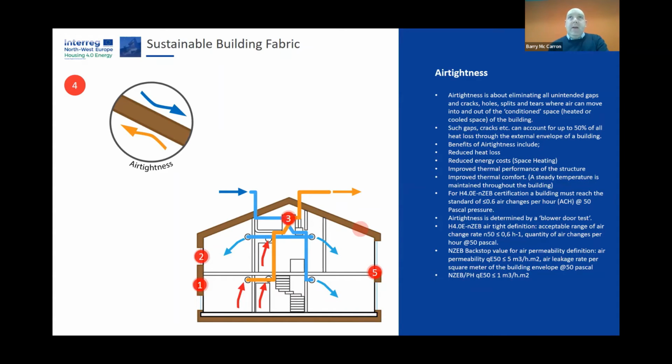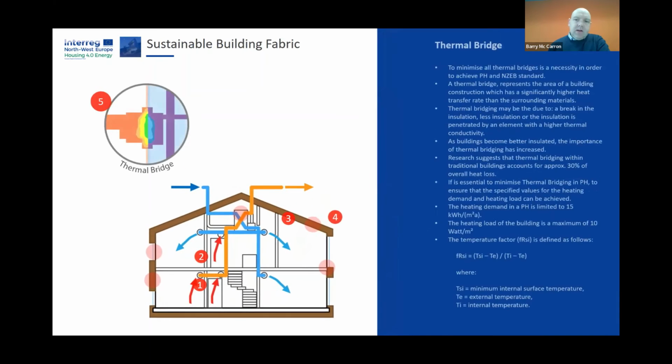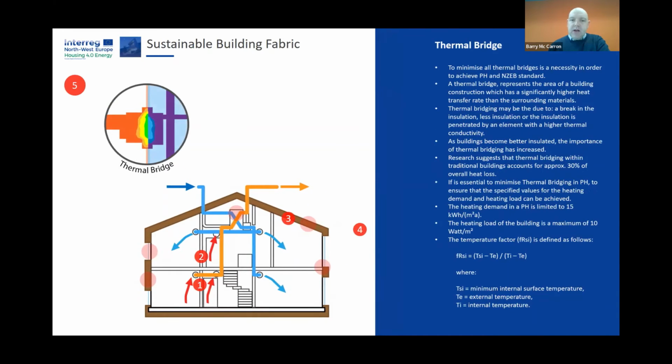And moving on then to timber buildings, typically where there's a timber frame building, you're really using tapes and membranes in many situations there as well. So that's air tightness. And then the last one again is the thermal bridge. I talked about some of the science around that. Typically we want these details to have no surface temperature lower than 16.